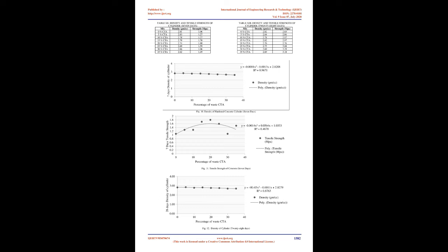Coarse aggregate. Some of the tests done on coarse aggregates are discussed below. Flakiness and elongation index. Flakiness and elongation index for two sets of aggregate was done. The first set is natural crushed aggregate and the second is crushed tile aggregate. Flakiness and elongation indices obtained are shown in Table 3. Flakiness and elongation data of crushed aggregate: sieve size range, mm; weight, gm; flaky aggregate, gm; remaining weight, gm.